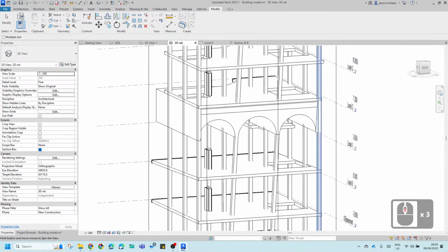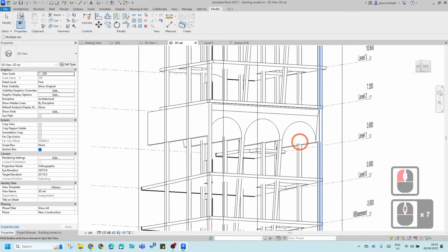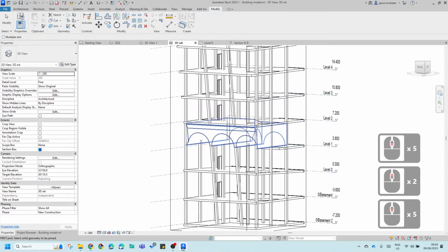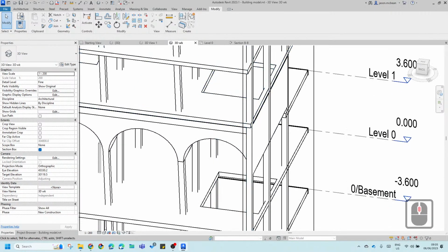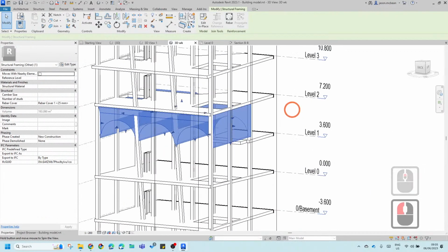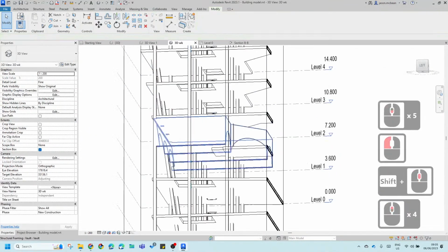So when you cut through there, it will look right. Now you can join that with that. If you join that to the floor slab and there's already a void cutting through it, will it automatically cut through it there? Oh no, you'll have to copy that and make an extrusion to cut through it. I'm going to have to edit that void anyway, so I can just leave it. That's the only downside to in-place families.